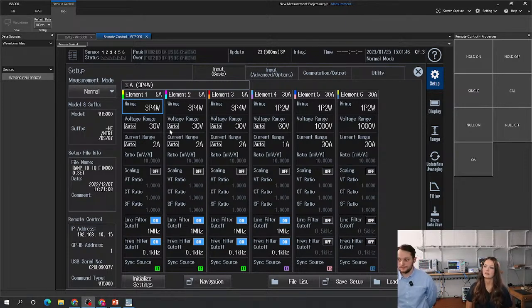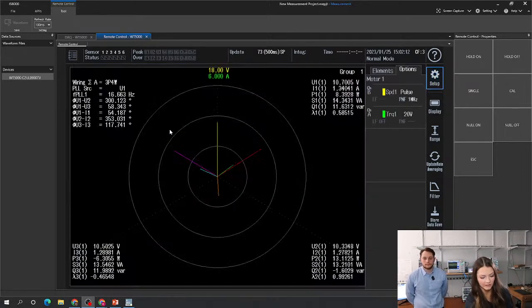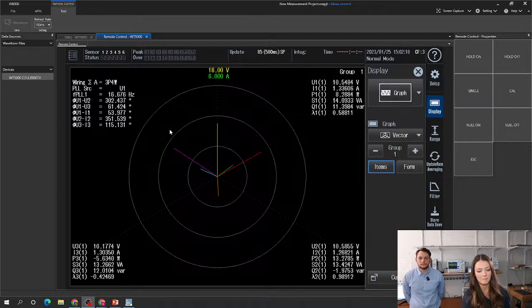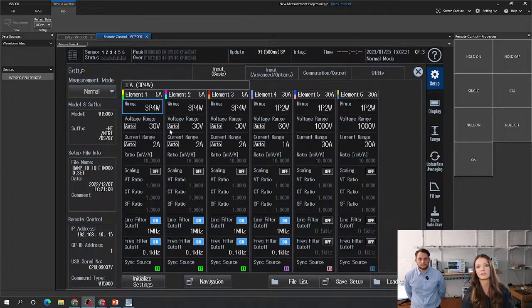Essentially, instead of connecting the voltages to each other, like phase 1 voltage to phase 2 voltage, it would be phase 1 voltage to neutral. And yes, that's available here. We don't have anything with a neutral, so we can't make those measurements here, but anyone that does, I can still set it to this. It's just going to do the calculations. It messes up the vector diagram because it's expecting you to see something else, but it'll still do the calculations. You can set it to that, but this would be for if you have that neutral available.